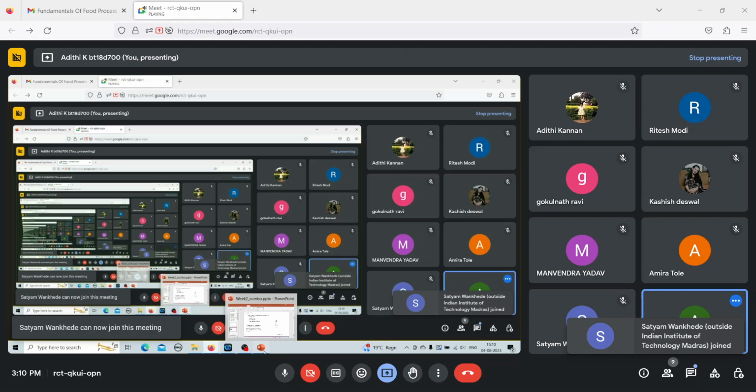That force travels through the elastic part of the series and the dashpot part of the series as well. This model is known as the Maxwell model and was one of the first models developed to understand the viscoelastic nature of the fluid, rather the simplest model used to describe it. So this is Maxwell's model, spring and dashpot connected in series.